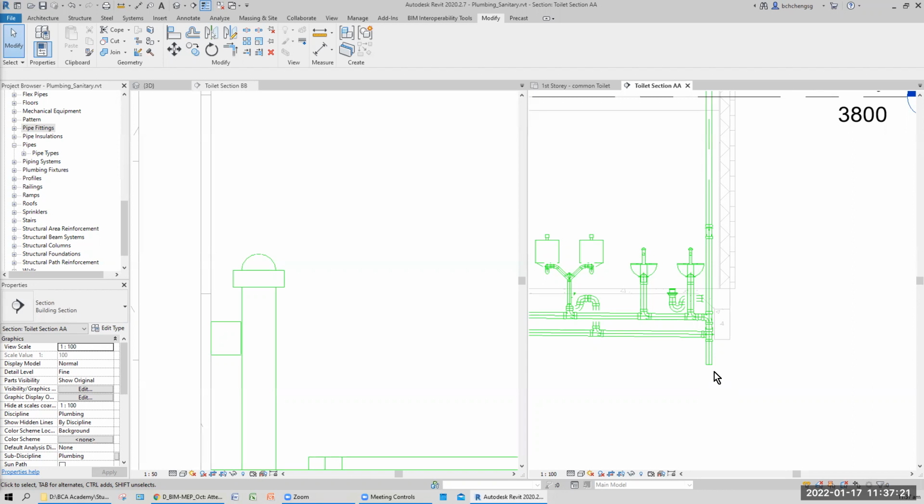Of course, if we talk about high rise, the water cannot go up anymore. So they need a pump to pump the water to the last level, and you have a storage tank. Based on the storage tank, you let the water flow naturally, which means they have certain pressure, but sometimes not strong enough. So they need a kind of booster pump to pump up the water. So when you talk about all this, from below up to a certain floor, and from the top down to a certain floor, it opens this way to supply.